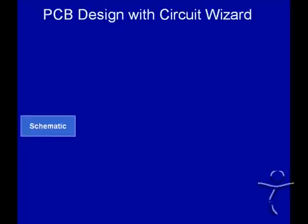This presentation looks at the best way we can design a printed circuit board or a PCB with Circuit Wizard and TechSoft PCB Design and Make. We first start off with a schematic or plan for the design. This plan has the components and the connections. In some cases, we can even simulate the operation of the circuit.